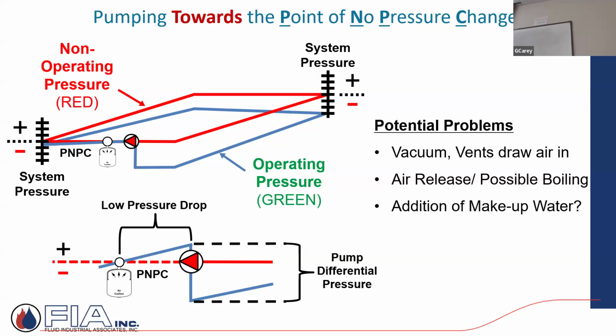They're pulling air into the system, and they're creating air gurgling, air binding. And this is why he wrote the paper years ago: the guys didn't know any better because it was all in its infancy, these hydronic systems as they got bigger. So they're putting these big pumps on the return because residentially they were putting the smaller pumps on the return and it seemed to be working. They put them on the return, and all of a sudden they get sectional cast iron boilers corroding because of oxidation, because they're bringing in so much oxygen every time the pump turned on. And if it wasn't that aggressive, it was just the air binding or just the noise, the gurgling of the air.